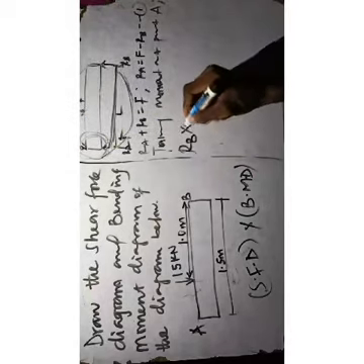So taking moment at point A will now mean RB force times the distance it's covering. RB is covering a total length of L to this point. That is RB times L. Okay, and that is what? Clockwise equals anticlockwise. So this one is moving and this one is moving. RB is covering this total distance to here, and F is covering what?